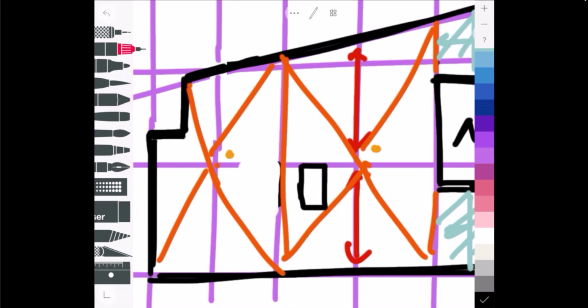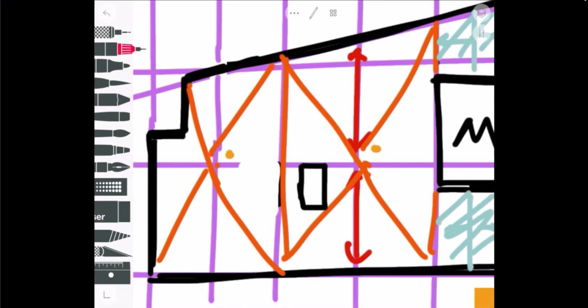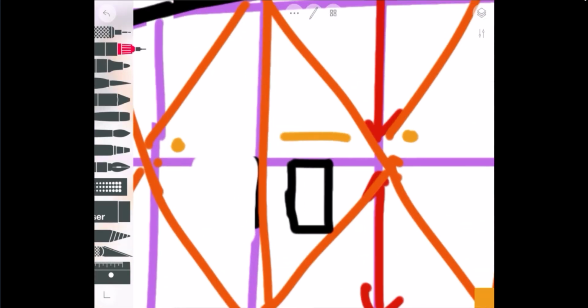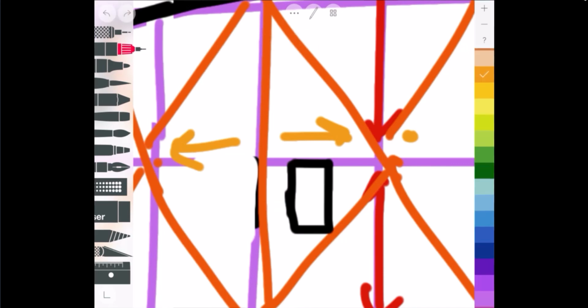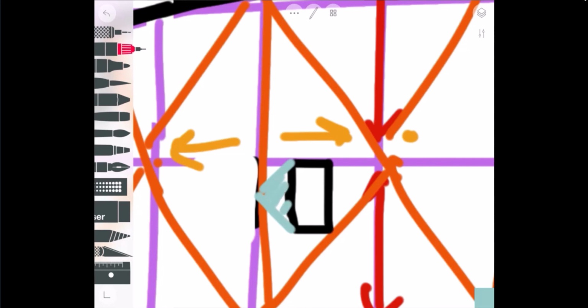So when you look at this, the water is now draining down this way and this way right here from that high point. So water is going to be draining here and getting stuck against the curb of that rooftop unit. So you don't want that. So there's always little places on the roof where you have what we call crickets, little built up insulations and crickets like that. So water is forced around that item.